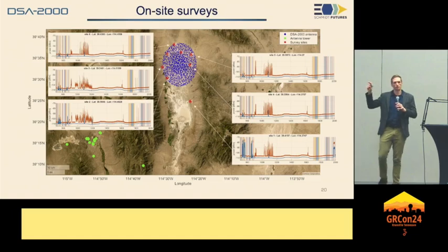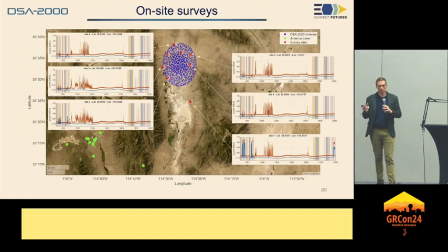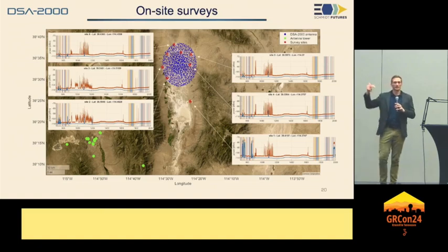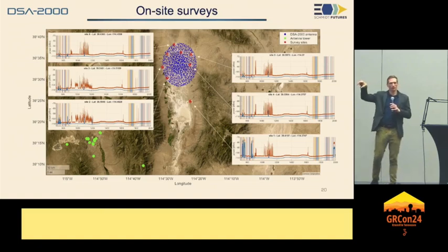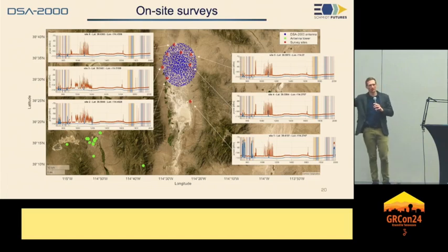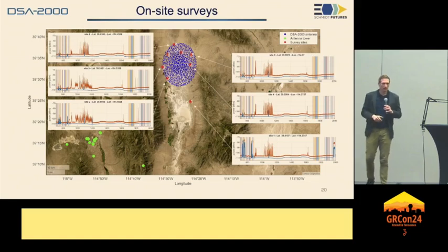You see those large signals, which are just the downlinks of that cell tower, which you don't see anymore in all those other spots, the 7 other monitoring points. That's just because the mountain naturally provides us with roughly 40 dB of attenuation from that cell tower, which is great.